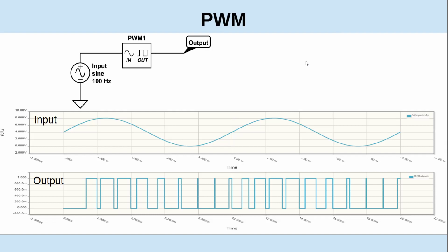And the filter is just going to be an LC circuit, could be just a low pass filter, whatever. You basically want to get rid of all the harmonics on these square waves. So it just needs to be the cutoff frequency a little bit higher than whatever the fundamental is that you're trying to get.